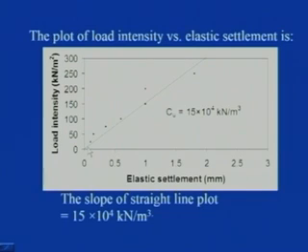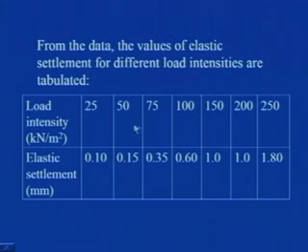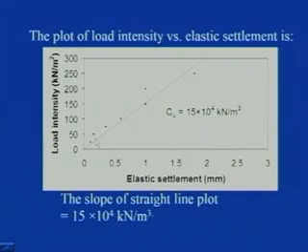You know that when the experimental data are there, they do not fall along a line properly. So, you have to take the best fit of that. These are the data points which we are getting from this particular table, and those data points have been plotted, and then a line has been fitted such that its slope we can find out. So, its slope will be giving us that Cu for the test plate.